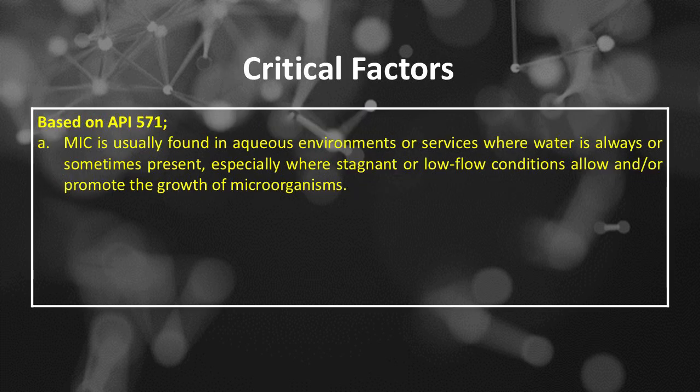Microbiologically Induced Corrosion, or MIC, critical factors based on API 571. Number A, MIC is usually found in aqueous environments or surfaces where water is always or sometimes present, especially where stagnant or low-flow conditions allow and/or promote the growth of microorganisms.